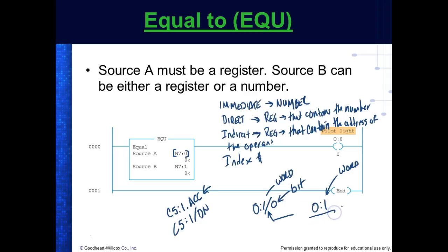But I don't do this right here because an output address is a 16-bit register. A counter has multiple 16-bit registers. So when I say counter 1, I have to specify which 16-bit register I'm interested in, right? You understand? So we have to put the dot. The preset register is a 16-bit register. One is for that. We have the accumulator, right? Yes. Preset. We can look it up, but there's actually more than one. Preset, accumulator, they do call it accumulator.